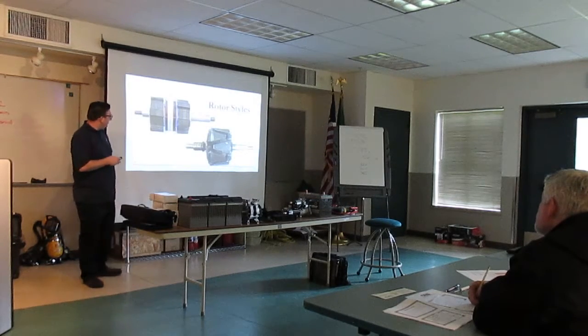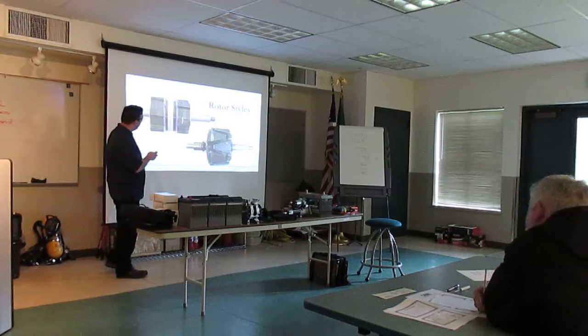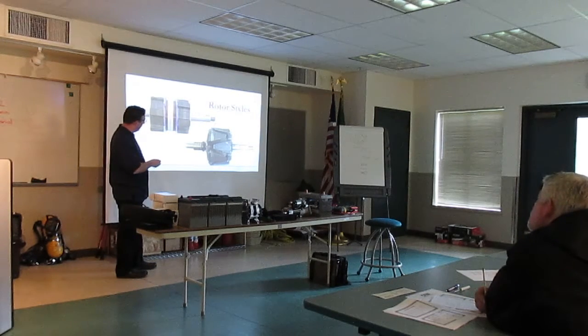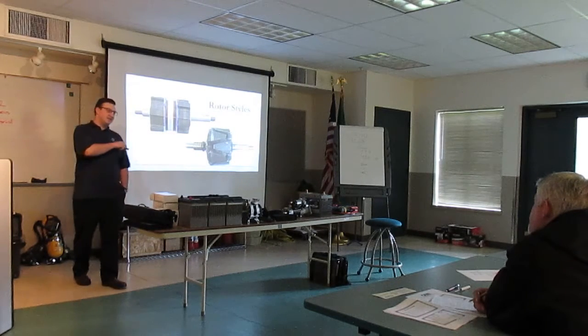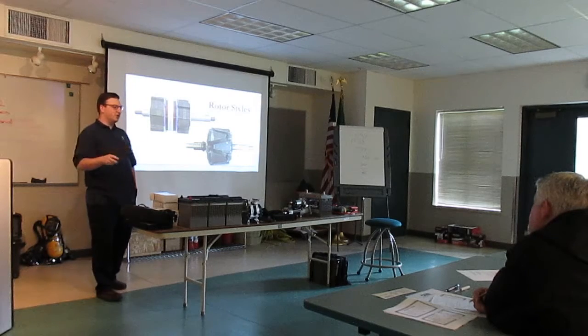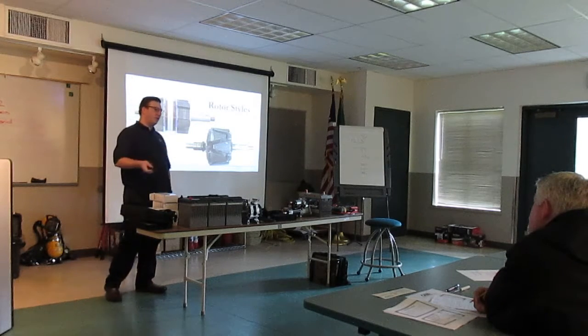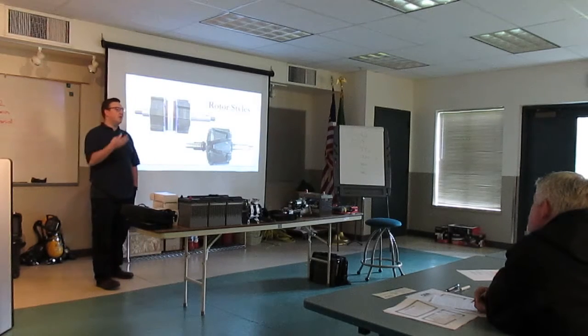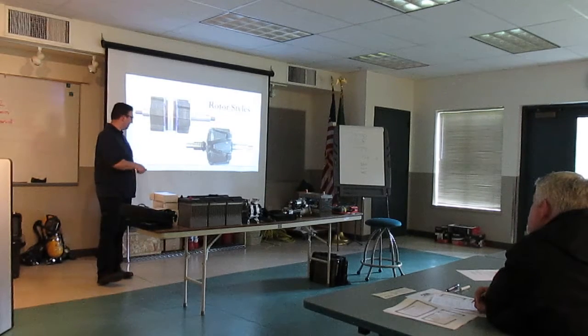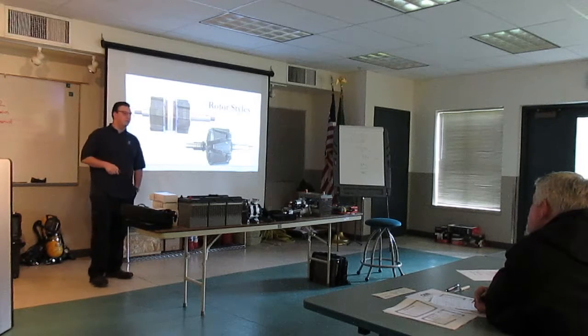As you can see, you have a couple of different styles here. We have our rotor and our shaft and our field coil. You have your rotor, your shaft, and your internal field coil with your slip rings and brushes. So if you have a unit that you know has brushes and slip rings, you're gonna have to make sure to test those before failing the unit. You might just have a bad set of brushes. You might just have some debris in the back of the unit that's stopping the connection.